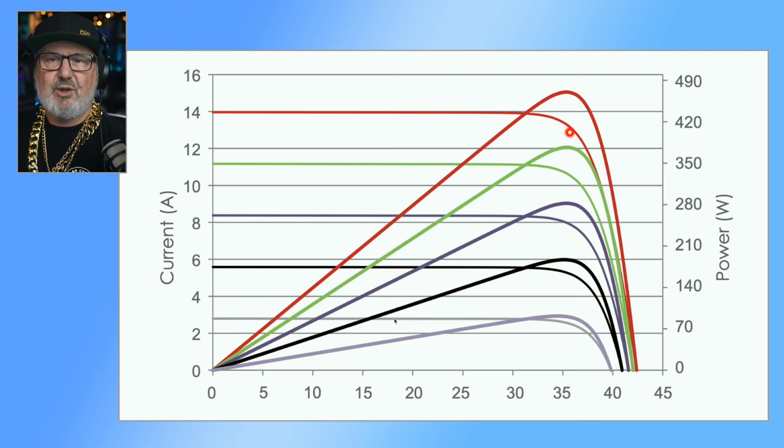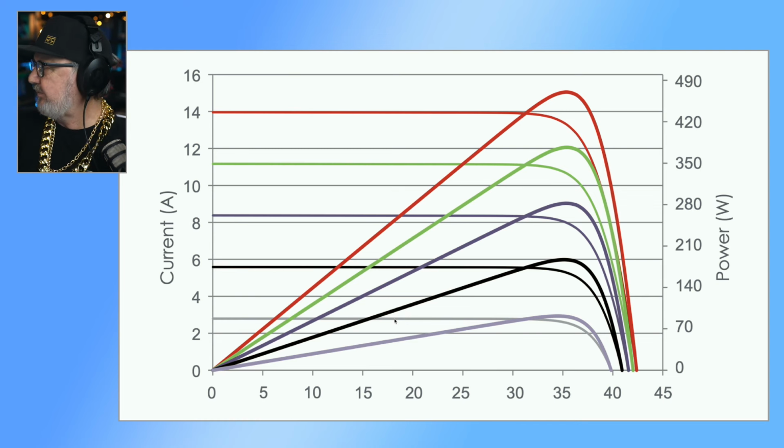what they call perturb and observe. Change stuff and see what happens, and then keep trying to find the sweet spot. Why doesn't it just lock onto that sweet spot? It changes all the time with temperature and irradiance. So as the sun goes behind a cloud, it drops down to here. So it's moved a bit. And behind a cloud again, it moves a bit further over here. And it's always moving quite a bit. So that's what a maximum power point tracking charge controller does.